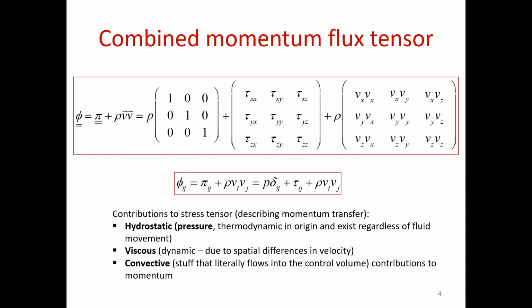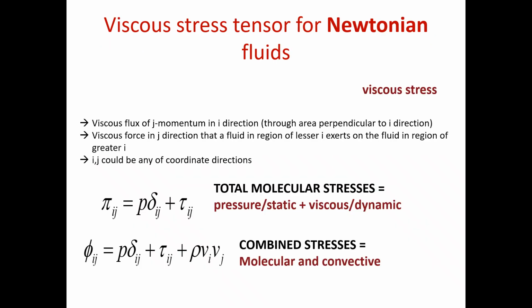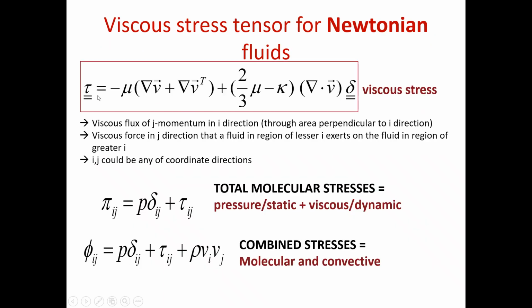That's the simple one. That generalized relationship is this: shear stress is I take the Jacobian of my velocity plus Jacobian transposed. So this is all of the partial derivatives of my velocity. Velocity has x, y, z components. So all partial derivatives in x, y, z directions are filling in a matrix as well, right?